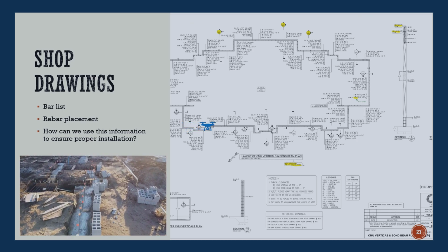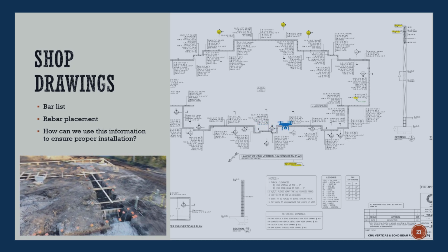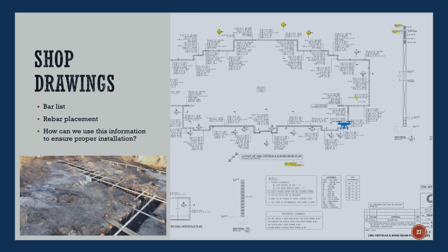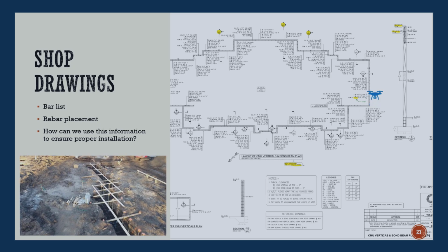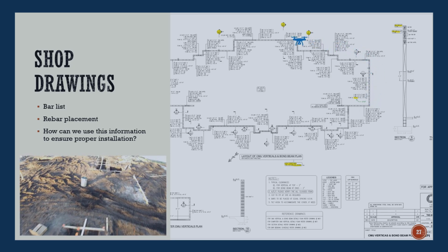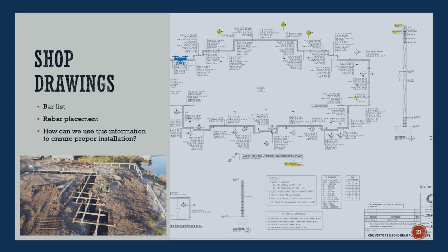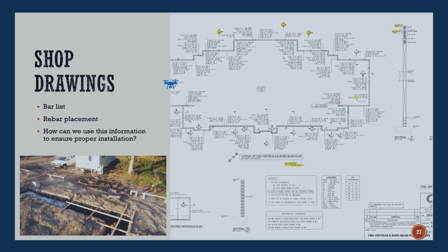The shop drawings can vary depending on the company creating it. These are based off the structural plan, so they may not note everything you need. The shop drawings are meant to be cross-referenced with the structural. But what all rebar shop drawings have in common is a bar list. We will get into greater detail about rebar shops and the bar list in another separate rebar course.